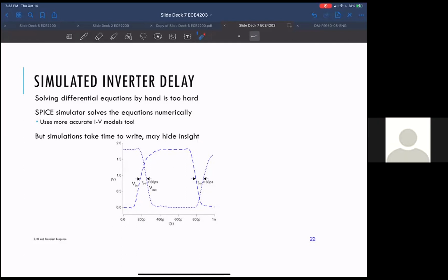Yes. So if you look into it, there's something called a .measure statement, .measure. If you pop up the LTSpice help, or just go on the web and look for .measure statements for Spice, you can use it to measure all sorts of stuff. There's a little bit of a setup involved. There is a chapter in your book.